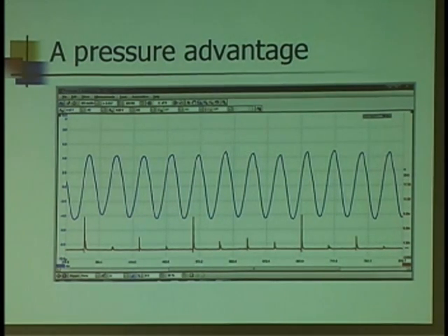If I had weak rings, I would find one of these smaller than the other. If I see them like this and they're all uniform, but my first test showed a weak cylinder, what can I go back and tell my customer? We need to take the head off. You got a problem upstairs. Again, how long do these tests take? Not long. How long would it take you to do a traditional compression or cylinder leak down on a transverse V6 to find the same thing? Okay?